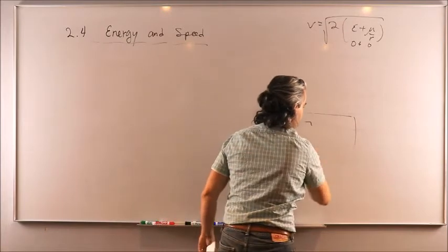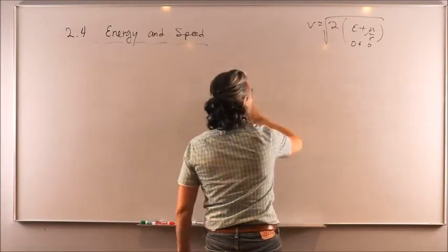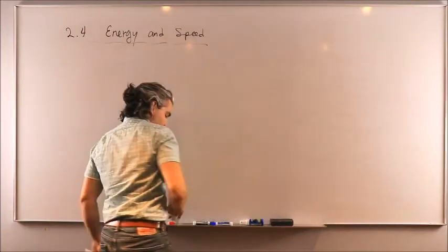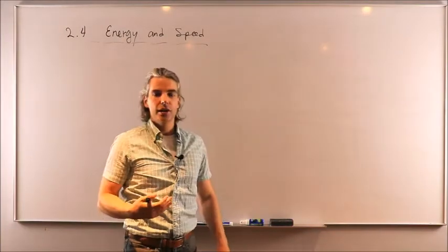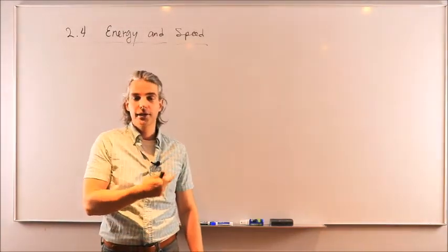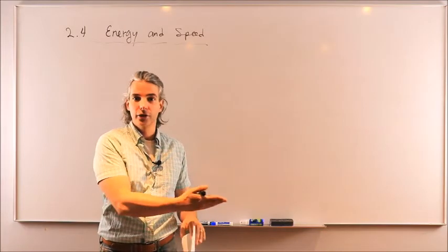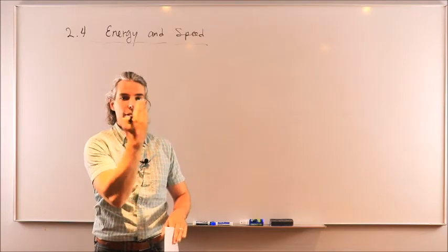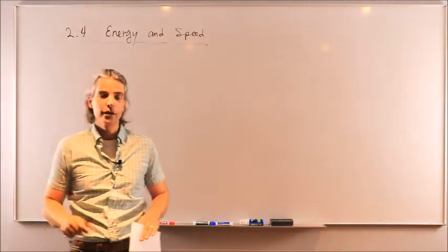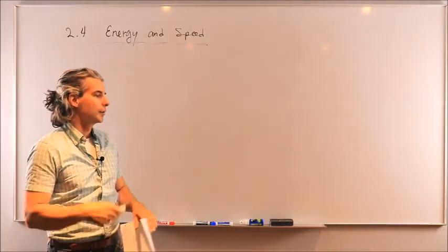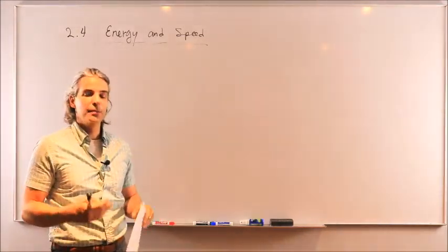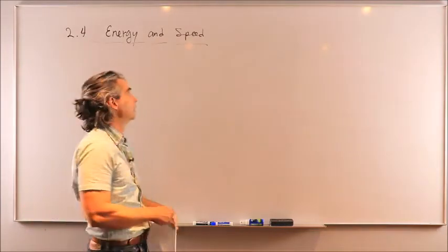Now we're going to move on to 2.5, where the objective of 2.5 will be to derive expressions that will allow us to relate the true anomaly, or the angle between the eccentricity vector, which is fixed, so that's our fixed reference, and the position vector that keeps rotating around as the spacecraft rotates around M1, to the time, because so far we didn't have the time explicitly appearing in our equations.